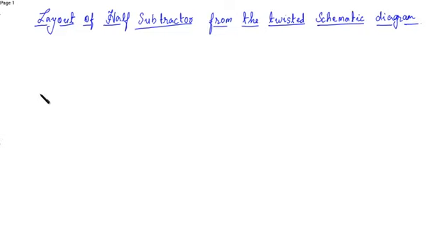First we'll draw the n-well and then the P diffusion layer. So I think this much space is not sufficient, so since there are 6 PMOS, we'll take a larger area.